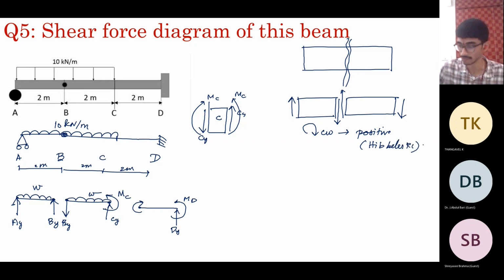And following the same thing, one of the textbooks mentioned for this particular course. So with respect to this sign convention, a positive Ay means Ay acts upwards. We don't know By, but this is a simply supported beam. This particular segment doesn't have any moment, so it acts as a simply supported beam.